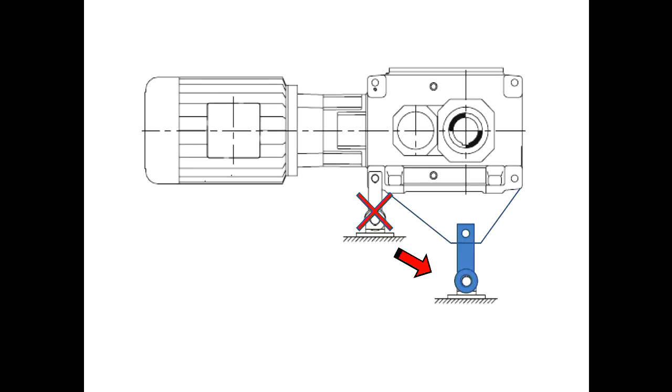I try and get that as tight as I can, because if I then pull this sideways, I end up with a force triangle like that, and a little force here is going to give me a big pull.